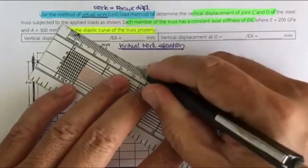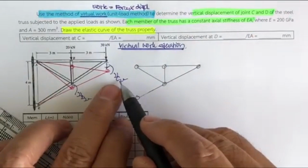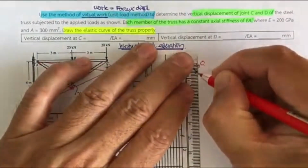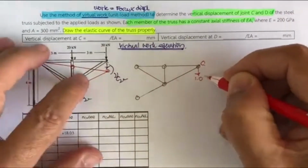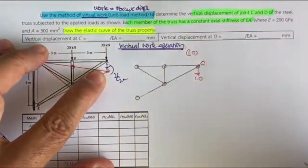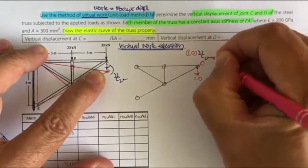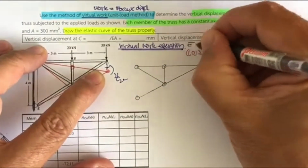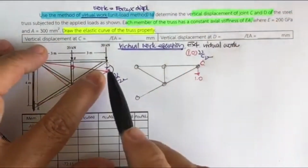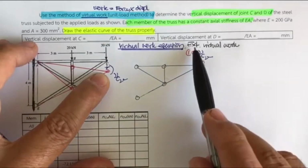What we have now, by the concept of the virtual work equation, is that we're going to determine V sub C, the vertical displacement at C, so we put the 1 unit force there. This assumed, or virtual, force times the real displacement of the truss at point C in the vertical direction is what we call the external virtual work, because it is the external displacement times the assumed force.